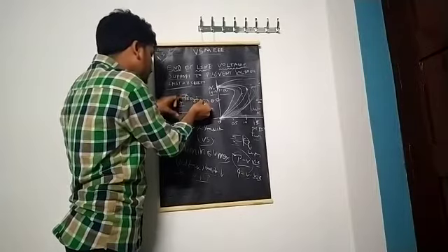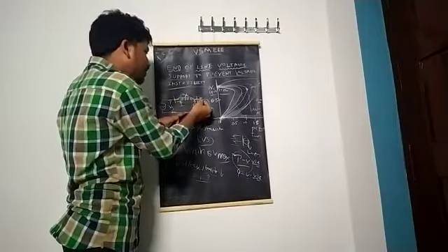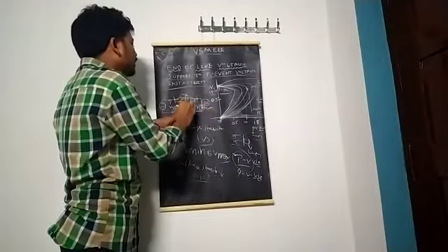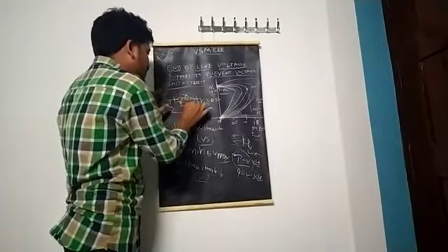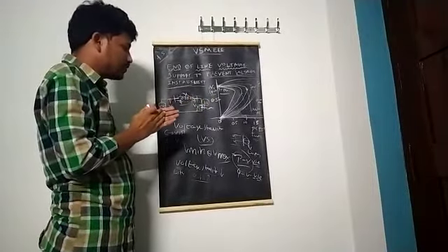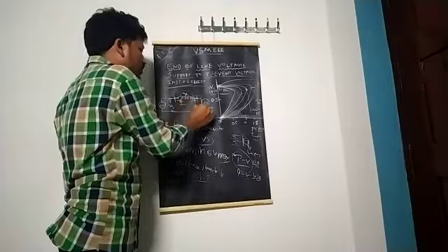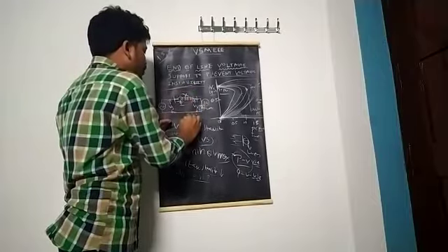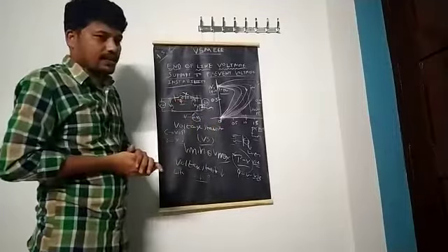increases. Indirectly, the current coming from the transmission line rises, and that is the current drawn by the load. That means while reducing the impedance, the current drawn by the load increases, and in this scenario the voltage drop across this transmission line also increases, but at a very small rate. From no load condition to a small increment in the load, the impedance offered by the load decreases, the current drawn by the system, consisting of transmission line and load, increases, then the voltage drop, that is I times X, also increases, but not at a faster rate.